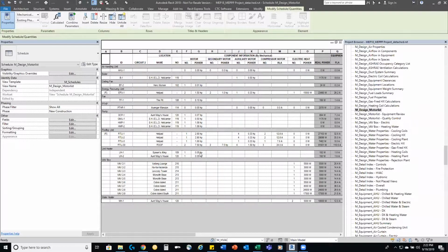And of course, we added overrides in here too for electrical designers, so that if you want to introduce a safety factor or you don't like the calculations that have come back as a result of the NEC 430s, you can put in whatever values you would like, and then of course circuit those values as well. So a lot of control there for both mechanical and electrical, and some good workflows to make sure that electrical design can get started earlier on in the process than they traditionally are able to while they're waiting on electrical loads for all the mechanical equipment.